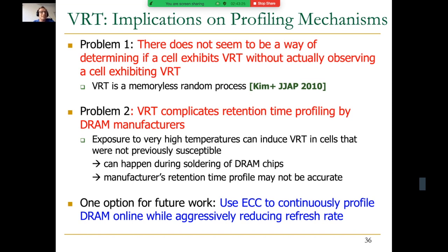It's a research problem in DRAM, but in flash memory, for example, there are a lot of error correcting codes, and things get corrected at the flash memory controller. I will actually talk about that very briefly if we have time later on. But this is another example of how you need to cooperate between the memory controller and DRAM. You should not really do things that are not transparent. And we may talk about that later on when we get to it.